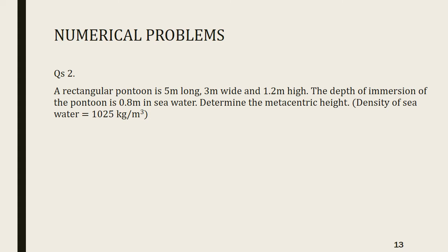This is the second problem. A rectangular pontoon 5 meter long, 3 meter wide and 1.2 meter high. So the dimensions are given. The depth of immersion of the pontoon is 0.8 meter in seawater. Determine the metacentric height. Density of seawater is 1025 kilogram per meter cube.